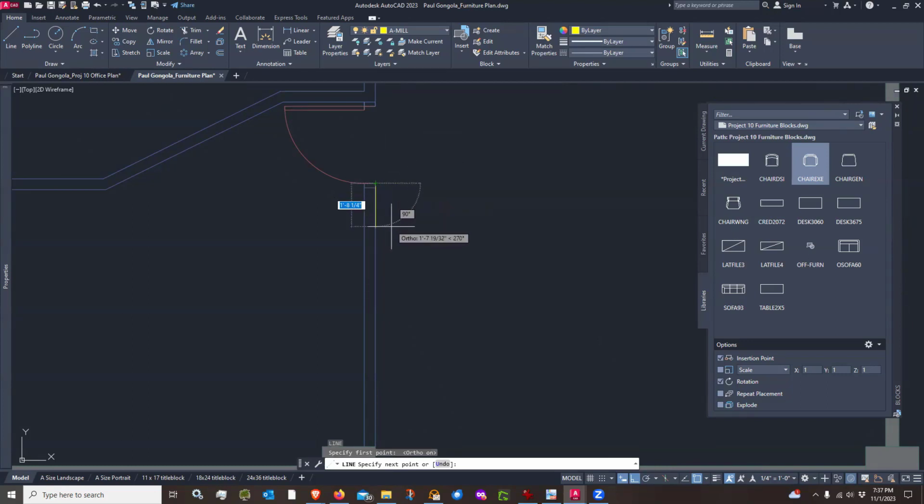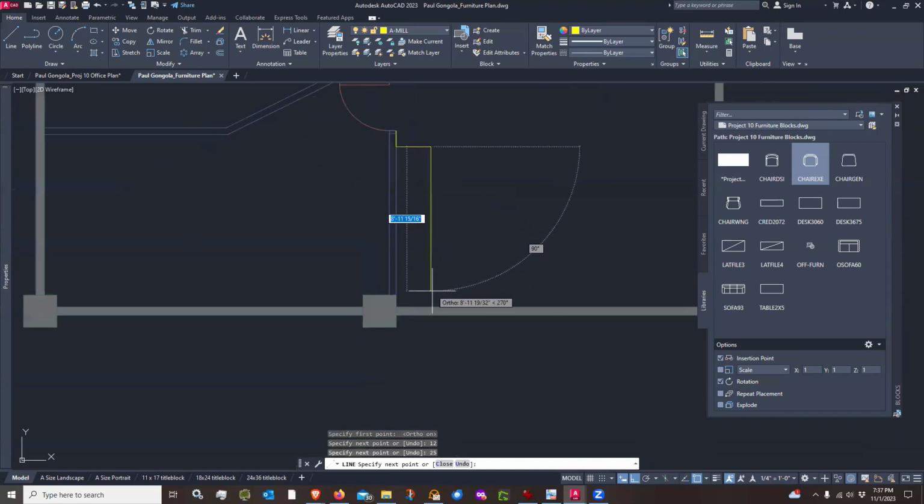All right, so now I'm drawing a line straight down, so I'm just going to draw the line, and then I'll come out 25 inches. It's asking for this to be 25 and go up 25. Okay, I'm seeing some dumb thing that I'm not doing. And oh, my object snap tracking is off. So that would do it.